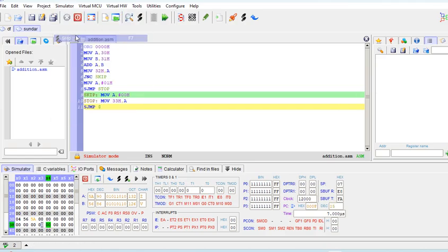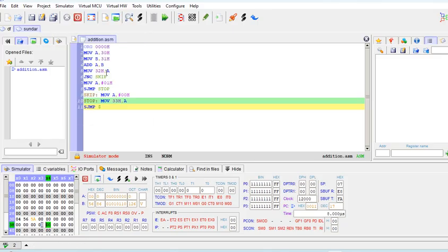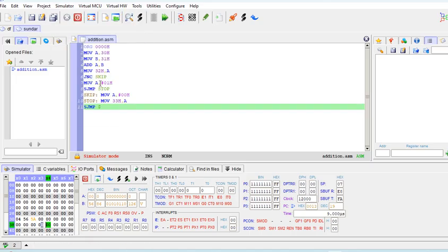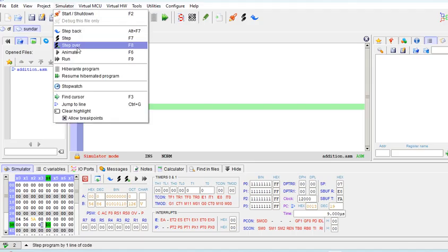Now one more step, now it will check the carry. Since there is no carry, it goes to the location move A, 00H. So 00 will be in accumulator. Now one more step, so it will store it in the location 33H. Already it is 0. Now it is 0 only. Then step, it will go to the last location, then it will complete.